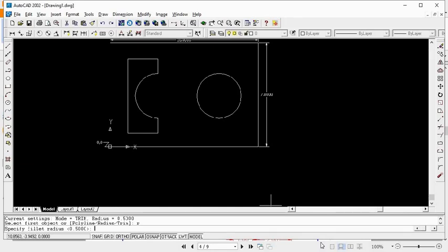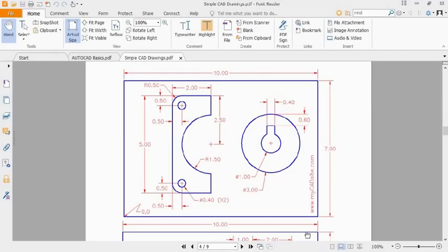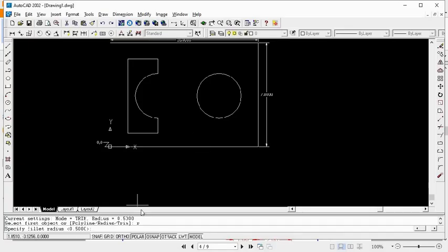You want to round with 0.5, is it? Yes, you can see the rounding of this corner is 0.5, so it is okay. Enter that, or the default one that is 0.5. So if you enter, it is the one that is picked. And then click the two lines that make the corner. Again, fillet, and now with the current settings, do the fillet again. So it has worked out with the second fillet with the same current settings that I had earlier.